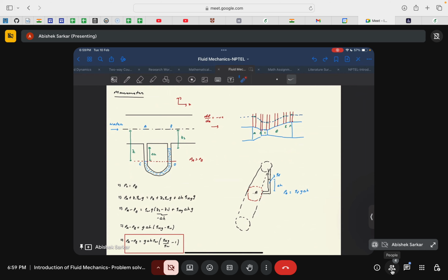There you might have seen some tubes inserted across the length of the venturimeter, which are basically piezometers that are used to find the pressure at different points by taking into account the liquid height at that particular piezometer.